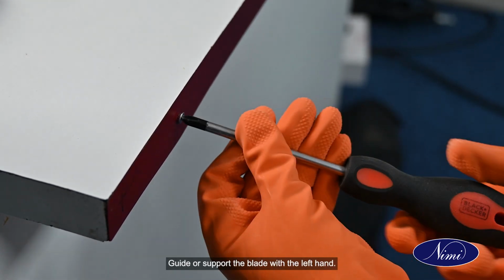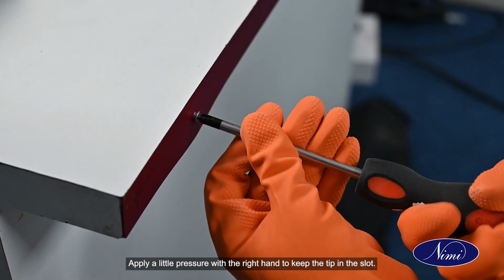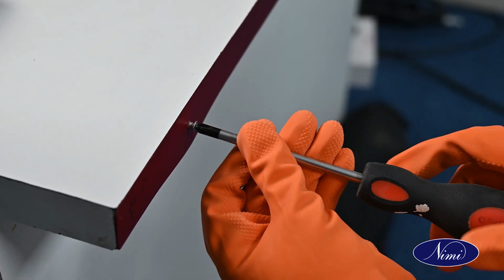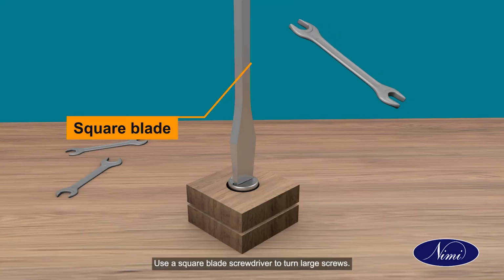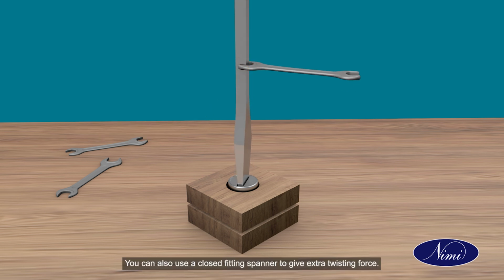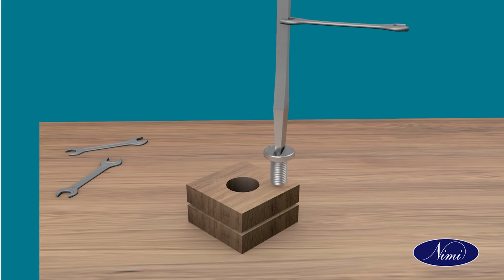Guide or support the blade with the left hand. Apply a little pressure with the right hand to keep the tip in the slot. Twist the screwdriver firmly and steadily. Use a square blade screwdriver to turn large screws. You can also use a close fitting spanner to give extra twisting force.